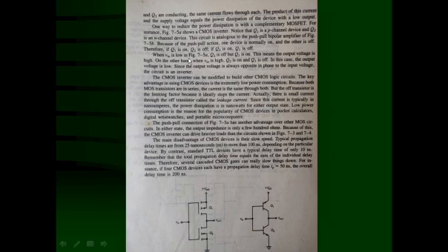When Vin is low in figure 7.5a, this Vin is going to be 0 volts. Which transistor is conducting? Here you can see that the P-channel MOSFET will be on, because the source voltage is greater than the gate voltage. So a P-type inversion layer is formed, and hence Q1 is conducting. But for Q2, the gate is 0 and the source is 0, so the N-channel MOSFET is going to be off. So this switch is open between the drain and source.